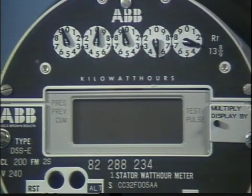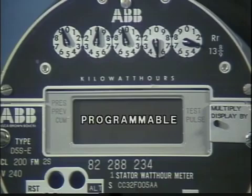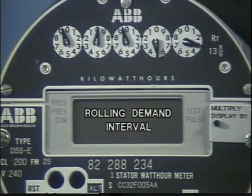The information that an electronic demand register can record, track, or display varies with the manufacturer, model, and how the register is programmed. Typically, electronic demand registers are accurate to within a few pulses. A pulse doesn't even equal one disk revolution, so accuracy is measured in tenths of a % of reading. Many features of the electronic demand register are programmable. For example, the register can be programmed to any time interval desired. The register can also be programmed to provide what is known as a rolling demand interval.